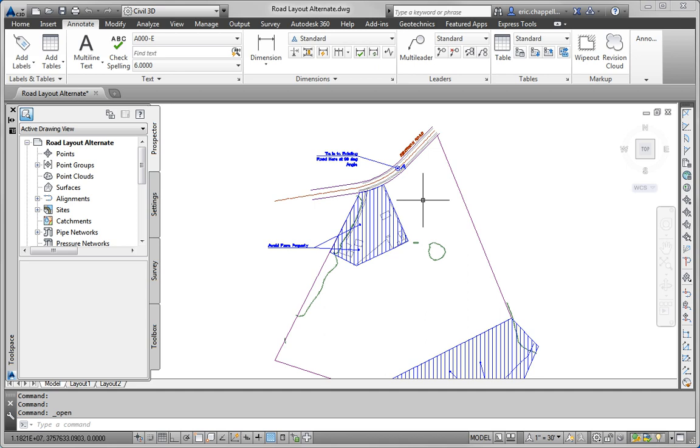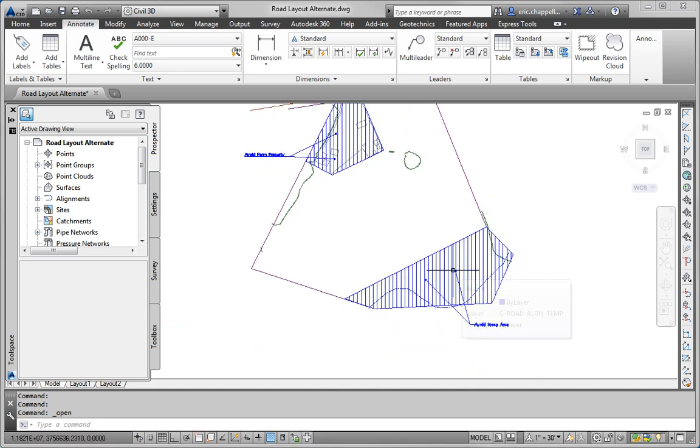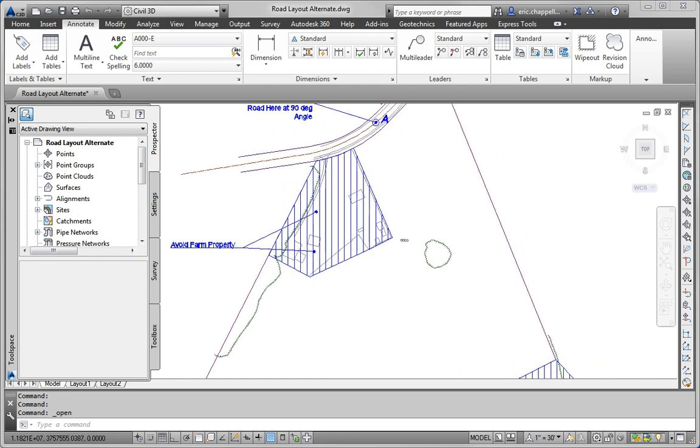We also need to avoid this area here, which is the steep area. We're saying the land there is just too steep to build on. If you did build a house there, the yard wouldn't be usable because the property would be so steep. We also want to try to use uniform geometric properties whenever we can: 90-degree angles, parallel lines, maybe even some even distances. And also, we know that this property right here is going to remain the property of the farmer, so we don't have that available to subdivide and create lots in.